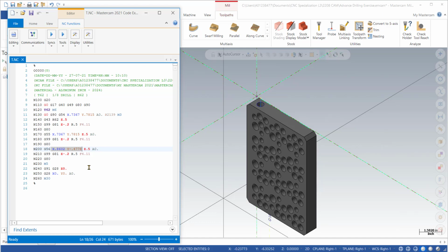So you see, by using the work coordinate system, you can accomplish more than one setup. There could be the same part, or there could be operations on different sides of the same part. You just set them all up, pick different work coordinates, and then establish your WCS in the CAM, and it will post all the G codes accordingly.